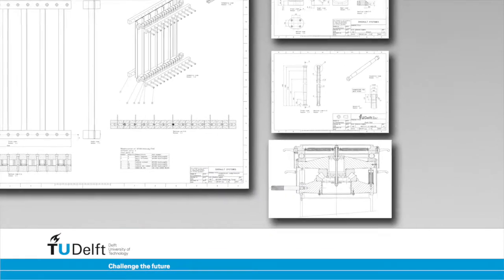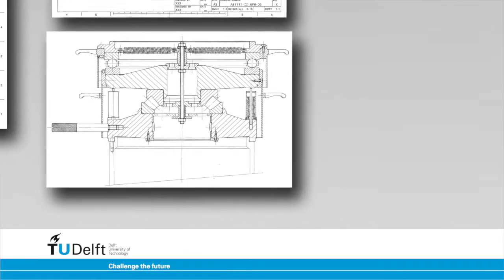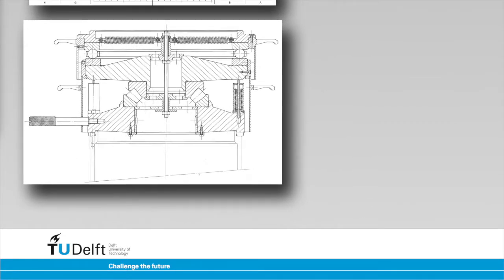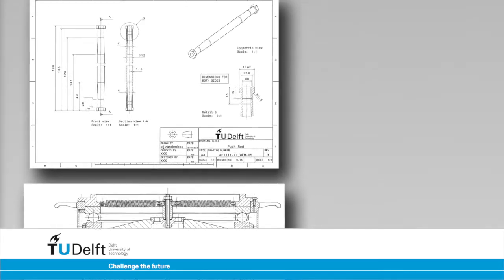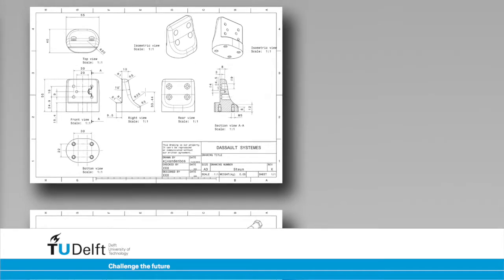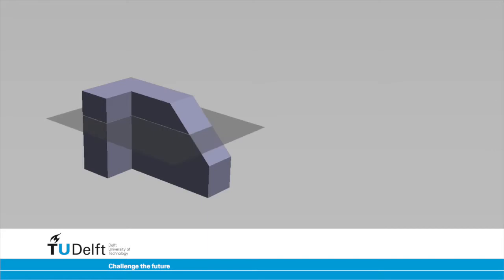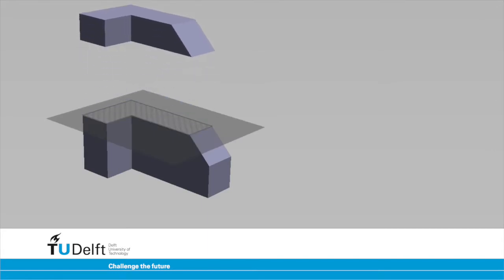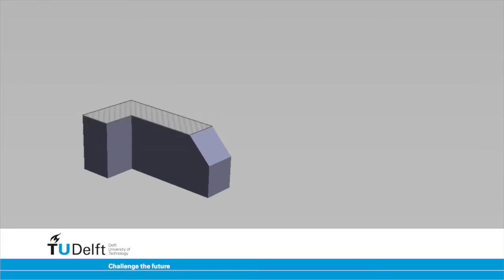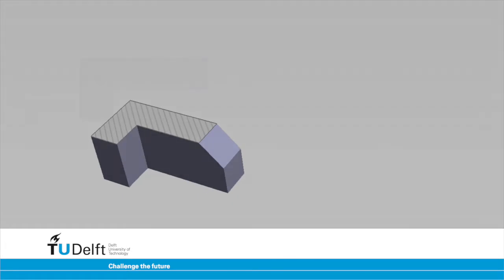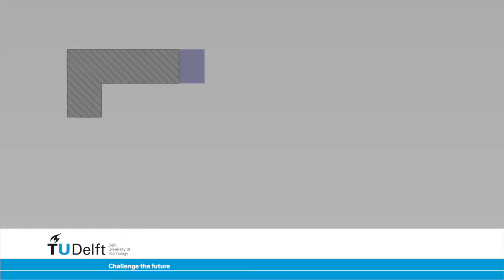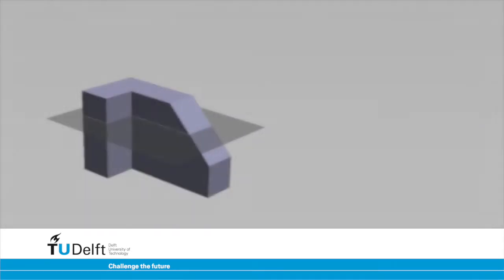Section views can be used in engineering drawings to supply information about local geometric items, such as internal features, profiles or shapes. Consider an object intersected by a plane. When the object is cut off by this plane, the remaining part will contain a face at the location of the cut. The orthographic projection of this face is called a section view. The plane used to cut the object is called the cutting plane.